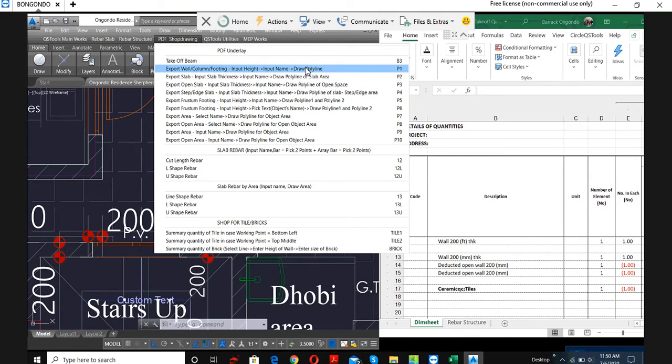This one, the PDF layout is used. Maybe you received the drawing as a PDF and you imported it, and maybe you group it together to avoid confusion. You know, a PDF is different from when you receive a soft copy of a DWG file or a DXF file. So this is where it makes work easy. But if you receive a DWG file, it means that the column footings will already have a square, or a rectangle, so you can just click on the object. Now if you are to do that, you don't use the PDF layout, you use the main works.